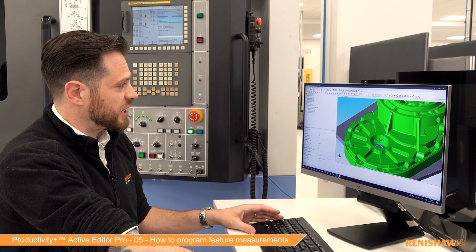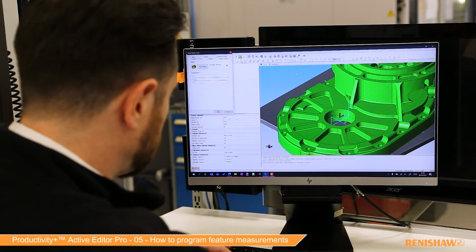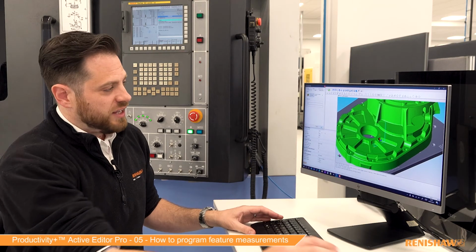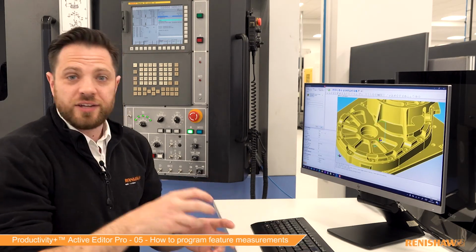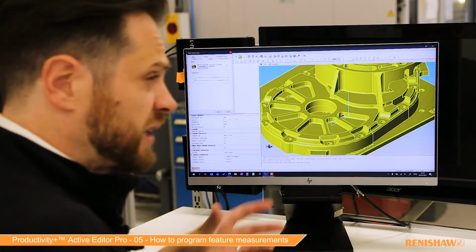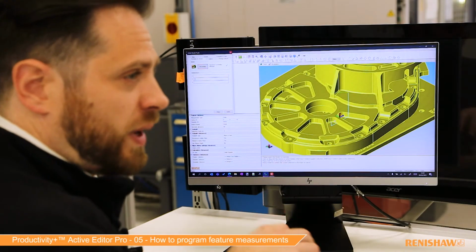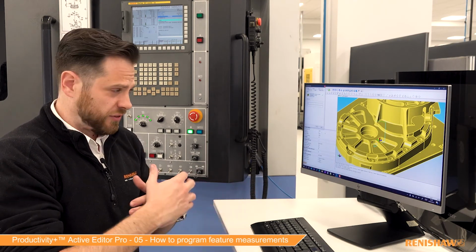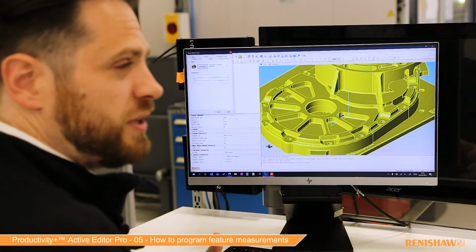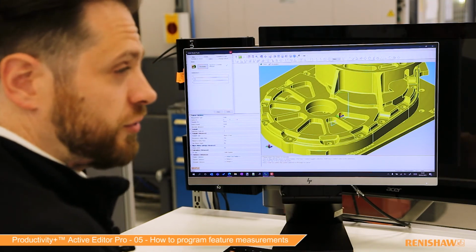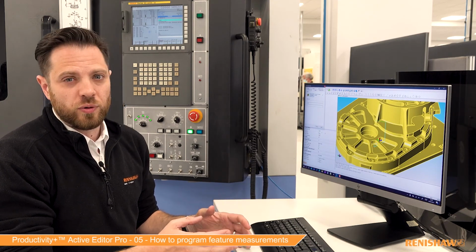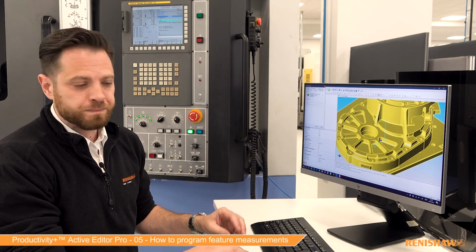And what that means is actually if I do that same activity and I move that 50 mil, what we'll see is actually that toolpath now stays with the coordinate system. So we could delete all these solid models out and all the toolpaths would stay. So a basic statement is exactly the same as the measure statement. It has the same functionality. It just means you can manually create those sizes and positions yourself, have them tied to a coordinate system, and you wouldn't need to import a solid model in order to generate a program.